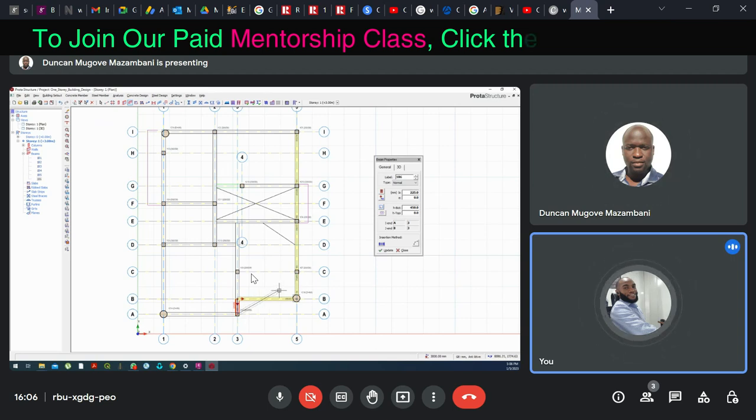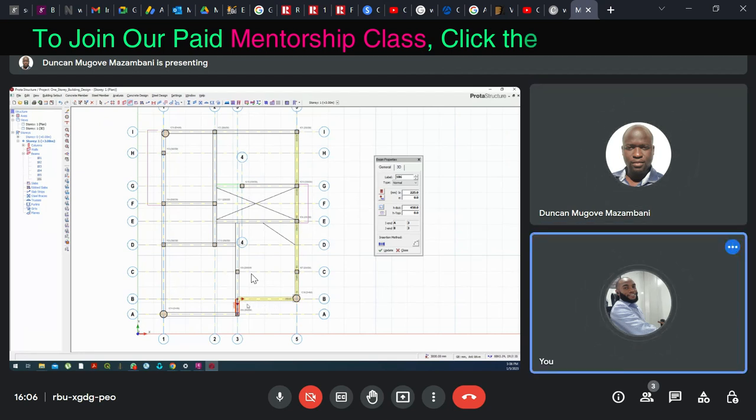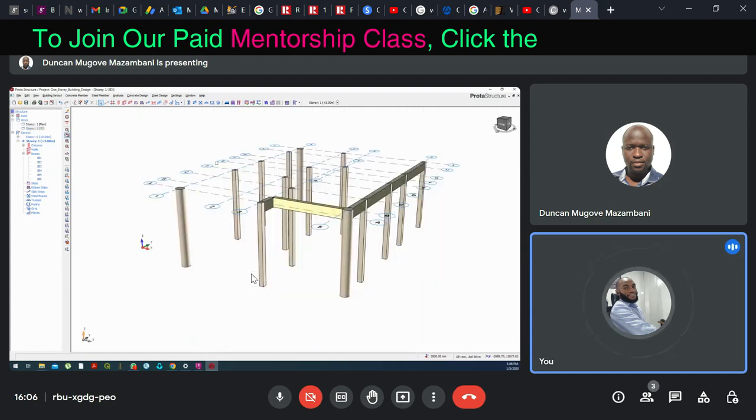To delete, just press escape first, and delete that one. That one right there is now acting like a cantilever beam. Just escape. Let me see your 3D view on that place. You see that it's acting like a cantilever beam. Go and click on 3D view. Then look at that place right now.